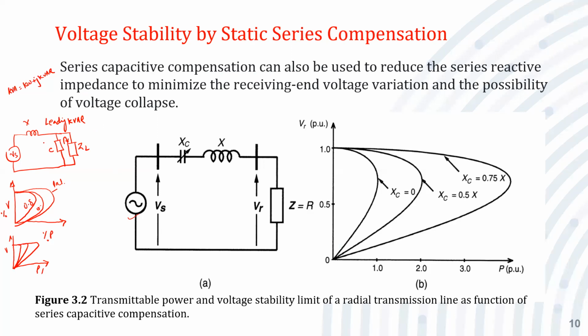So what is the difference over here? The shunt compensator is going to supply the reactive power needed by the load, whereas when we connect a capacitor in series with the transmission line, the total reactance of the transmission line gets reduced by some factor. It may be 30%, it may be 20% or 50% as required. So there are two different methods, but the effect is the same.